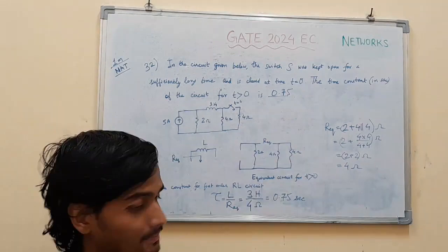One thing you can write is this. Another way is representing this. This voltage is the same as this voltage, so we can write this voltage here. So again we can write V1 minus 2 I1, replacing this with V2, so minus V2. So from here we get 2 I1 equal to V1 minus V2, taking 2 I1 from that side. So from here we get I1 equal to V1 by 2 minus V2 by 2.